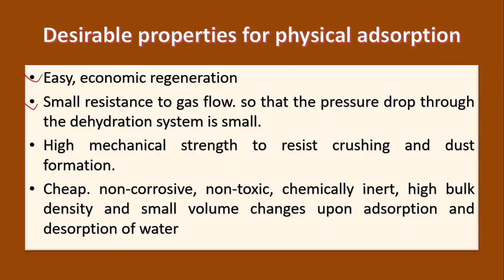A small resistance to gas flow, so that the pressure drop in the dehydration process is very small, because there is very little resistance to the gas flow. High mechanical resistance to resist crushing and dust formation. And cheap, non-corrosive, non-toxic, chemically inert, high bulk density, high volume change upon adsorption and desorption of water. So these are a few properties that are required for any material that can be used in the physical adsorption process.